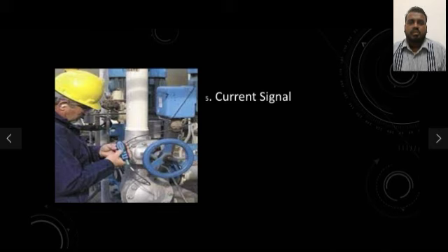In this condition monitoring technique, variation in the stator current caused by change in the magnetic flux density between the stator and the rotor due to the induced current is monitored using a sensor to determine the condition of the bearing.